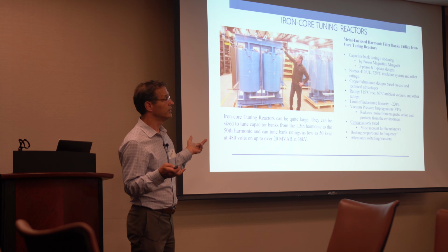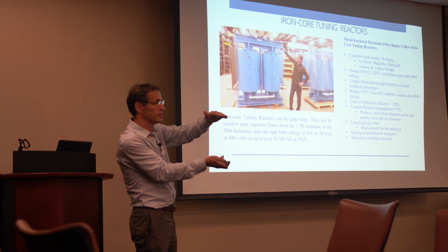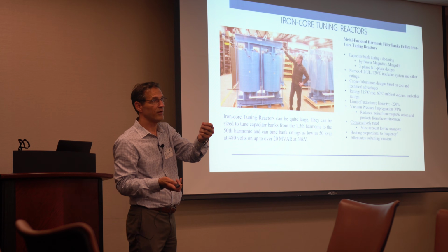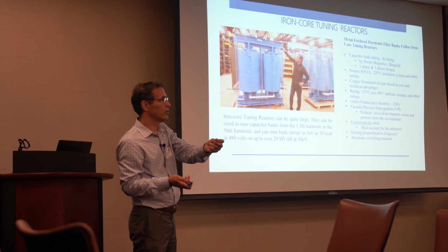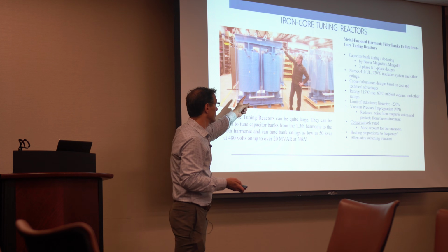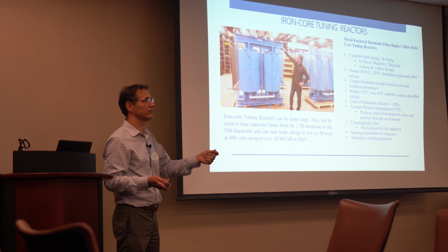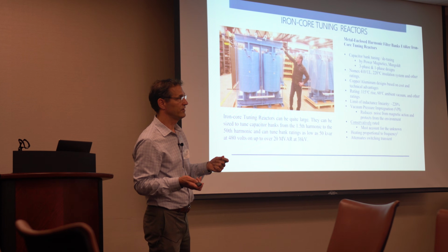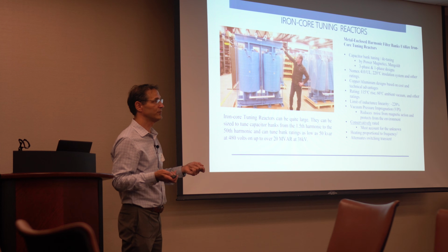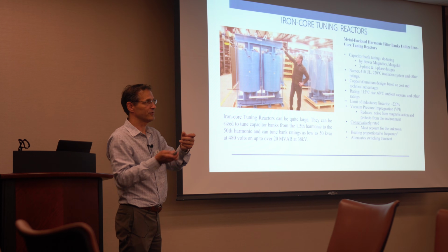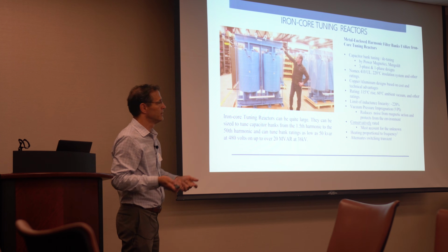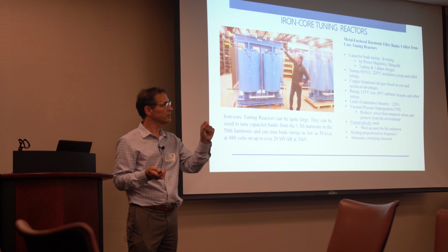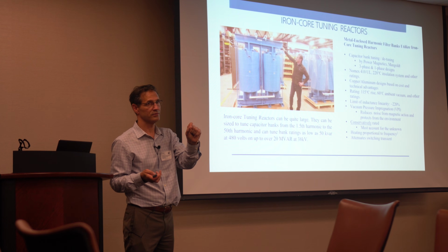So if the bank, the X of C, X of L, you take those two values, you calculate the kVAR output, and you calculate a nominal value for the filter bank of 100 amps at the fundamental, we will ask our supplier of the reactor, we want 150, which is a lot, but we're operating then at about 50% of its losses and 50% of the forces inside the reactor, so the thing will just sit there and be quiet. And then the harmonic value, we go by either 50% or 100% rating on the reactor.